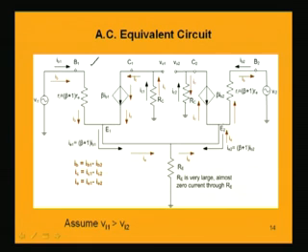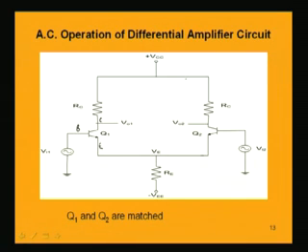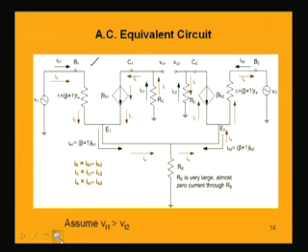and the current which flows in the collector is IC2, which is nothing but beta times of Ib2, and that is the current source which is IC2, and this current flows in this direction through this resistance Rc, because if you look into this resistance, the collector current will be flowing through this Rc in this direction towards the transistor. It is an NPN transistor, and that is why the base current and collector current will be towards the transistor and the emitter current will be away from the transistor. That is why emitter current IE2 is shown by this direction, which is beta plus 1 into Ib2.